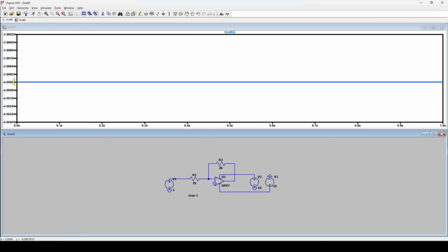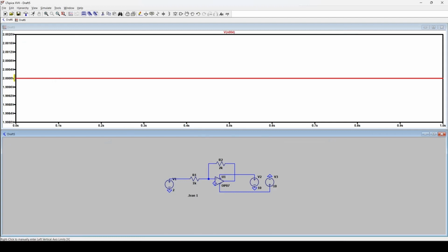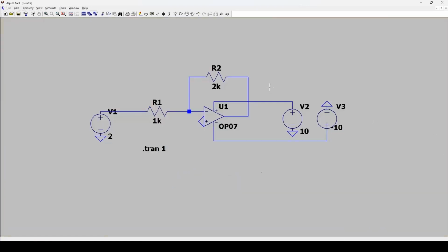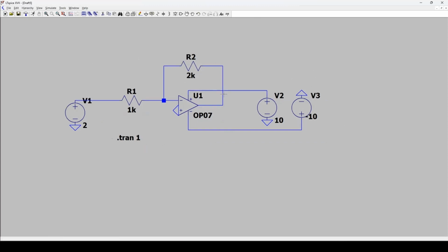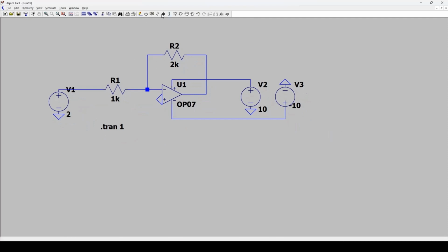So as we can see, we have a -4 volt output given a 2 volt input. And we can zoom in a bit closer by double clicking just to isolate it. And we can see it's at 2 volts. So we have a working inverting amplifier, but we're running into the same, I guess, kind of problem, but for now, not really, where wires are overlapping, which is fine for a simple circuit. But let's say we actually wanted to add a bit more complexity to our circuit by maybe stringing it alongside another operational amplifier.